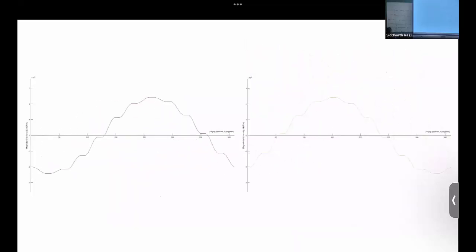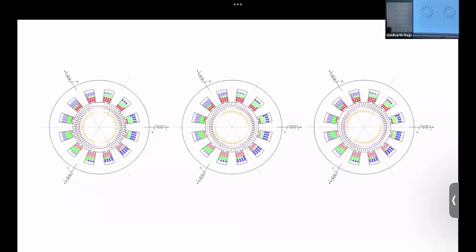And then again, here just a bit clear what's happening. So when we have all three phases, we would have the rotating fields of A phase, B phase, and C phase in one direction, and there are other rotating fields of A phase, B phase, C phase in the other direction. And our math shows that in one direction, the fields are all pointed at the same direction at any given time. In the other direction, they are phase shifted by 120 degrees. So the negative sequence components cancel out and the positive remains.